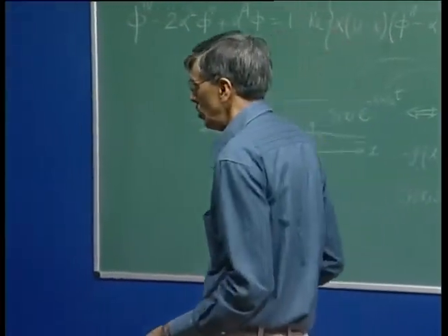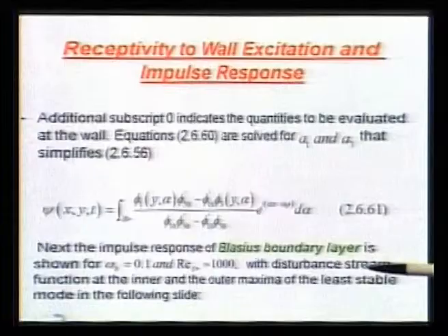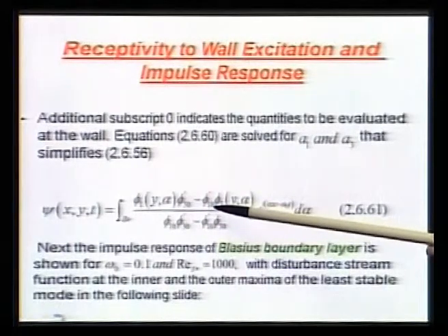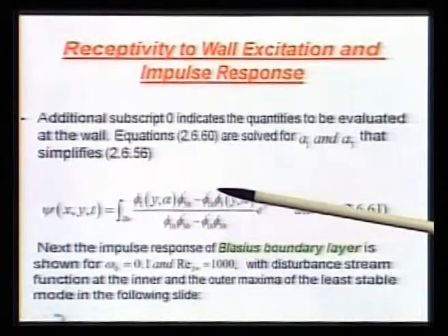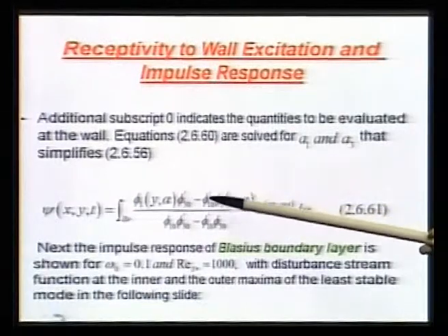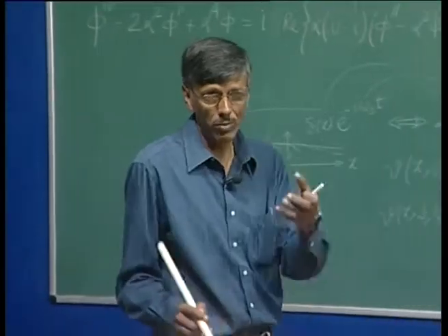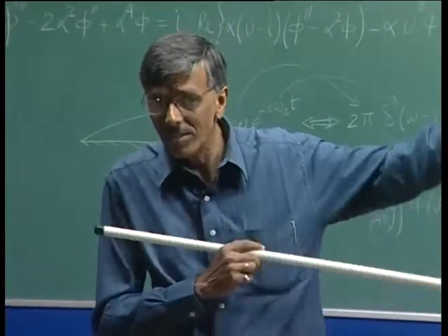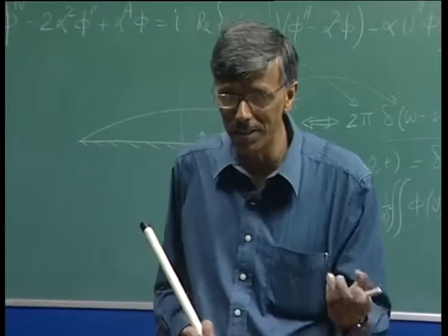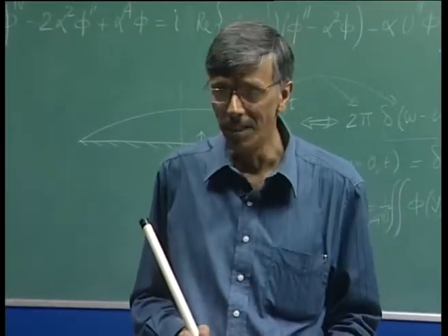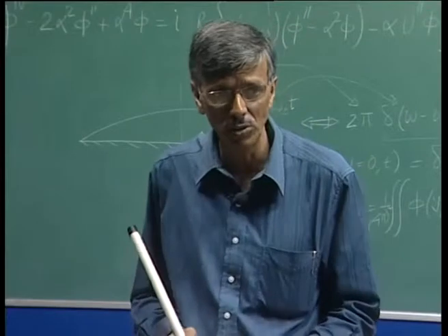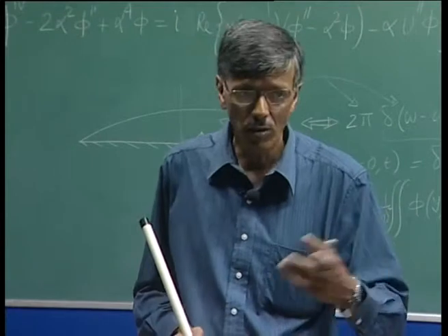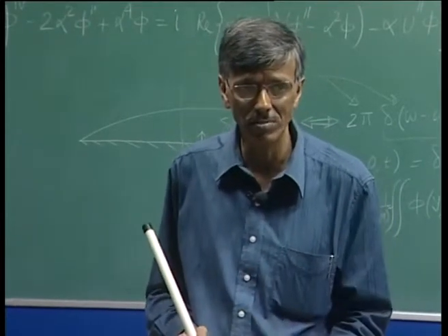There is though a case by which you could switch off this quantity. Suppose I can reduce the magnitude of this quantity, phi 1 prime 0 and phi 3 prime 0, then what will happen? If I keep on selectively removing them, I will not see that in the response. Remember the experiment of Reynolds. Remember the experiment that I showed you, flow past a cylinder for Reynolds number 53 case. For different speed, I have different background disturbance.